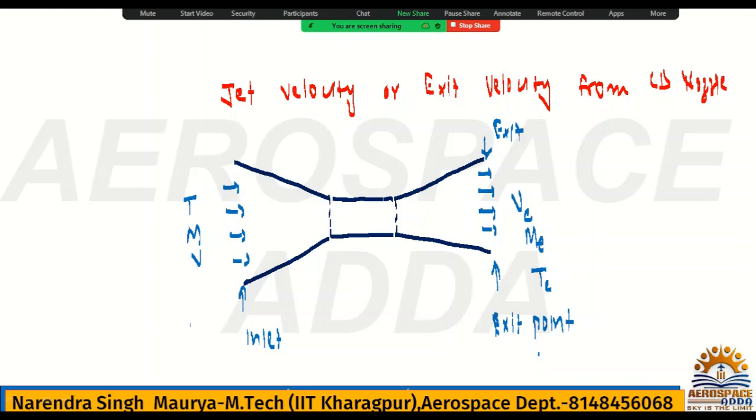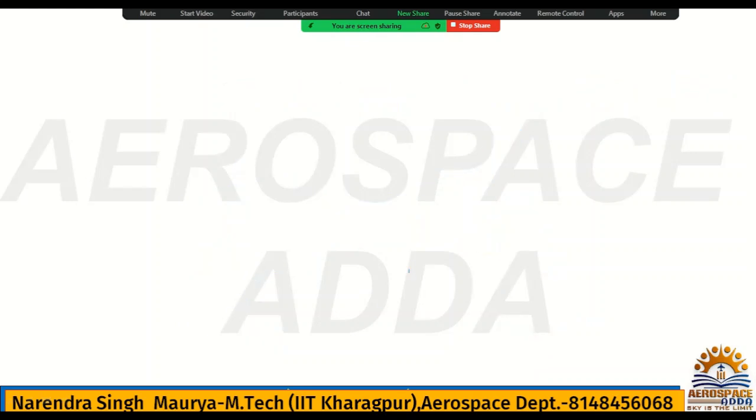From that condition we can calculate the total temperature. How to get total temperature? It's very simple. Total temperature T naught is equal to T plus V square by 2 Cp. This is the total temperature, T is called the static temperature, and V is the velocity.